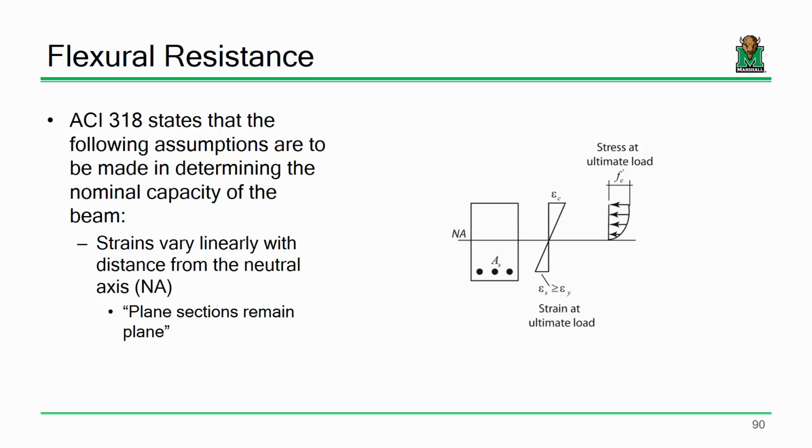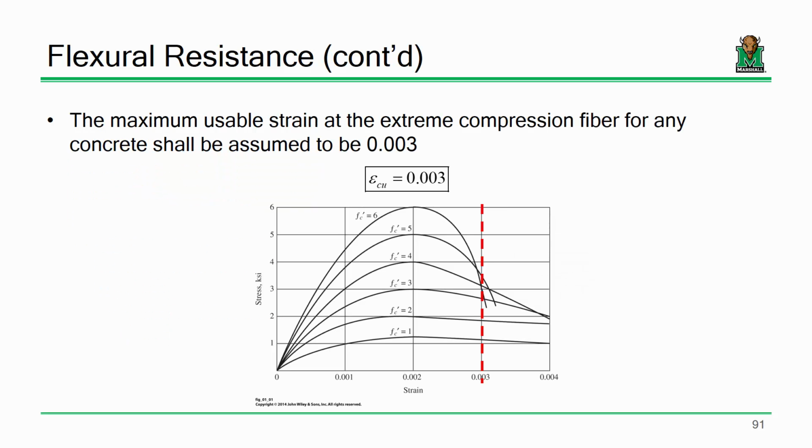And so that's a very reasonable assumption to make for a reinforced concrete beam. So even if you have nonlinear stresses, we still assume that we have a centroid or a neutral axis that has zero deformation, and then above that we have deformation in compression, and below that we have deformation in tension. Does that make sense? If you understand that, there's a couple things that you need to understand in order to fully define the strain profile for a beam. Okay? So let's talk about strains.